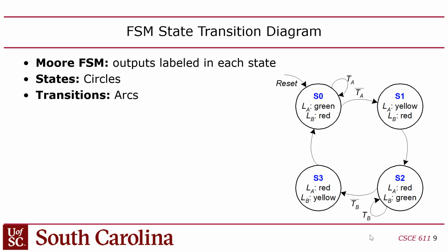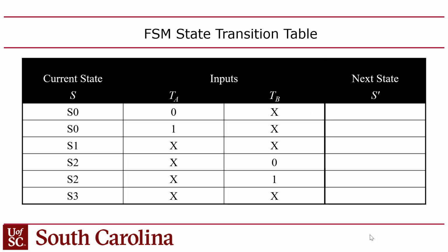So the divide instruction can be generated in Quartus if you want. You can generate a divider, and you can have it generate a multi-cycle divider where it goes through a sequence of steps. The controller that controls that divide process would be done with a state machine like this, right? So that's the more common type of state machine you'd have, controlling a divider circuit, for example, a multi-cycle divider. Okay, but yeah, the traffic light example is just used as an obvious example for explaining how you create these states and transition between states.